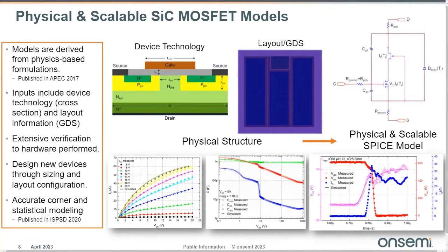On the middle curve, you have the output capacitance, and you can see on the blue curve the CRSS, where we can predict the sudden change of the CRSS linked to the fact that the depletion zone moves from the epi zone to the N+ region, and we have a sudden change of doping, and so a sudden change in capacitance